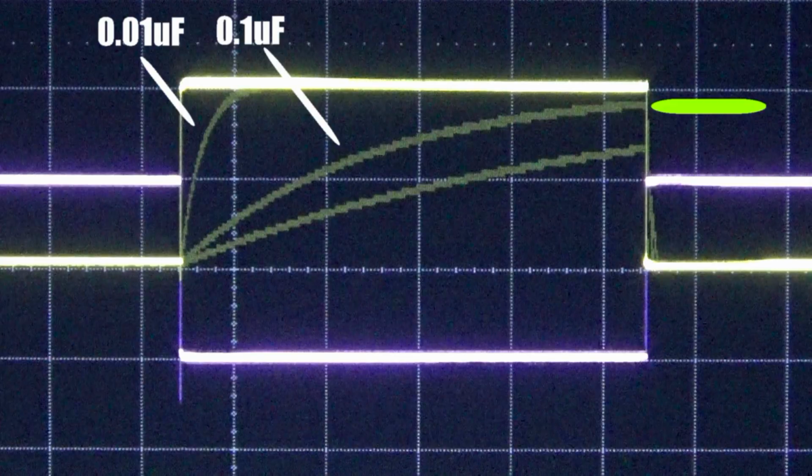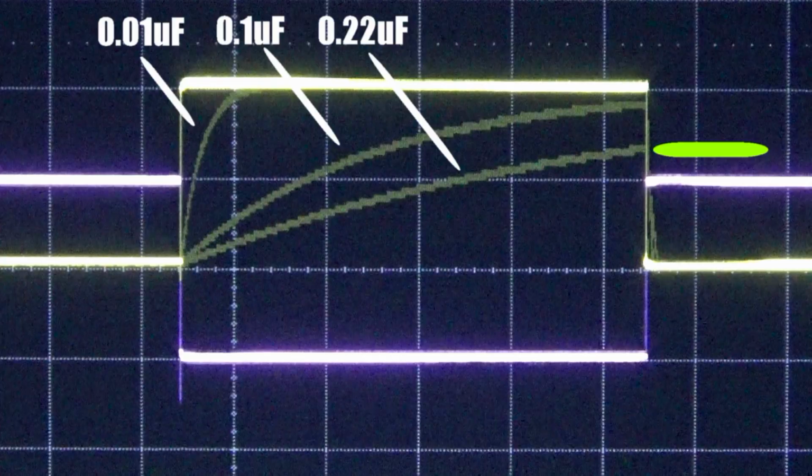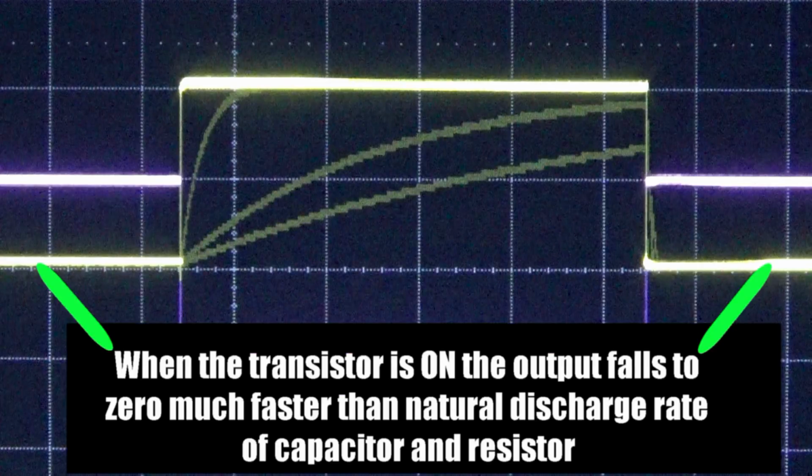Notice how we weren't able to fully charge up the capacitor like in the 0.01 microfarad case, where we fully charge the capacitor to the maximum output voltage. The last capacitor I selected in this waveform was a 0.22 microfarad capacitor. Notice how the amplitude is about half of what it was for the fully charged capacitor, but we get a more linear signal. We're getting closer to the sawtooth waveform. When we create the sawtooth, we're approximating a linear ramp and a steep drop-off, but we have to select the right capacitor given our input square wave.